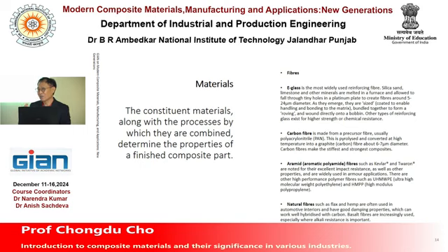But if you make it very thin, with a very small dimension, conventional E-glass is 100 micrometer, but these days E-glass is about 30 to 50 micrometer. 30 to 50 micrometer is about your hair, whose diameter is about 50 micrometer.